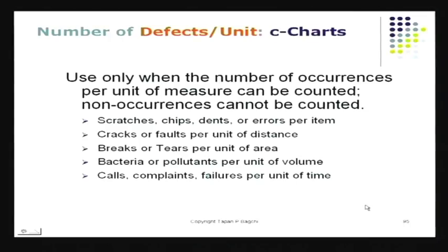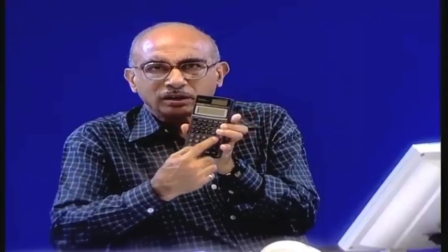These are quite easy. Another way quality characteristics could be measured is the C chart. The C chart is looking at the number of occurrences of defects per unit. So it could be, for example, if I had a calculator, I don't want to have a defective calculator, but say if I had sticky keys, or if the protective cover had some scratch on it, or the case cover did not fit very well.